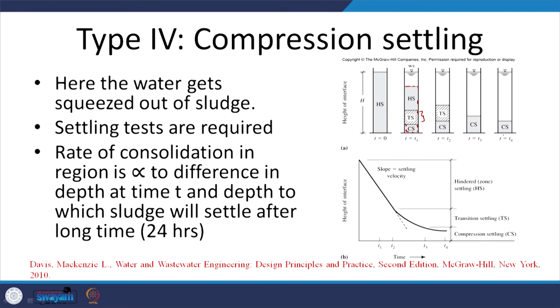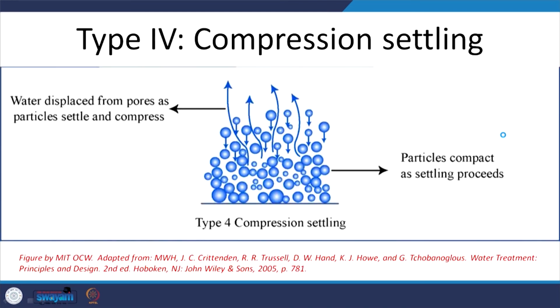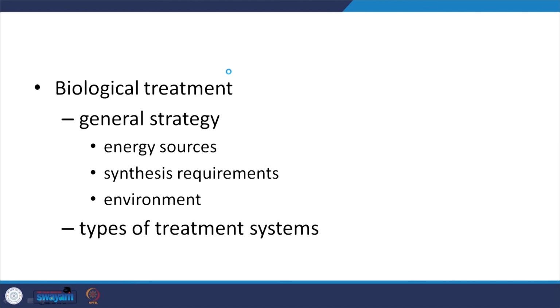And then we end up out here, right? So that's pretty much obvious, right? And again, as you can see, the weight and then all the water trapped out here is being compressed and released, right? So I'm almost done with my time, and we are also done with looking at primary sedimentation. So what next? I removed the suspended particles and some dissolved organic content and most of the suspended organic content. Next, I want to remove the soluble organic content, or the dissolved organic content, and that I am going to do with the aid of microbes, right?